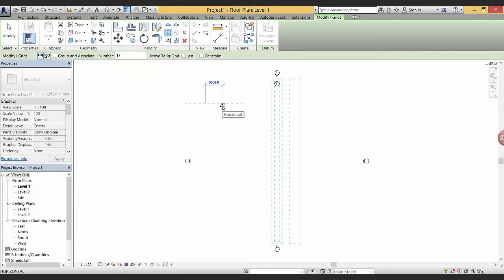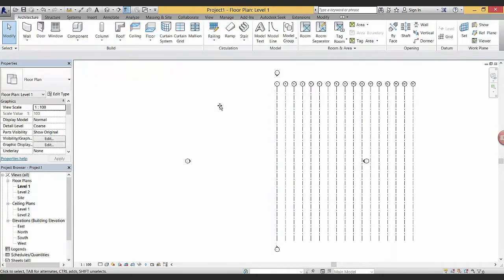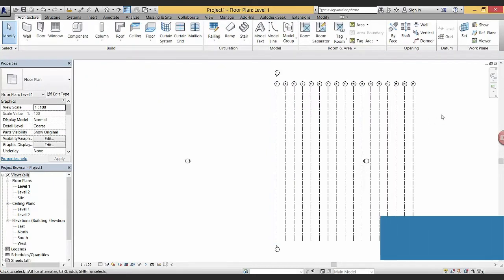Now when Revit asks for numerical input, like a length between grid number 1 and 2, you can either snap to a certain distance or you can start punching values on your keyboard. So we're going to type 2400 on the keyboard, press Enter, and voila, we have 17 grids.